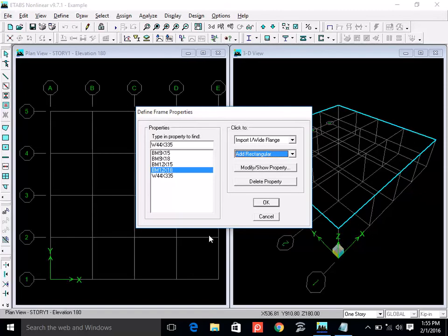So first thing you should do is ask for the drawings of previous projects. From the previous designs, you note down what sizes they are using, the format of the drafting, and how they write the general notes and other stuff. So you will learn the practice of this company, and then you can follow the same practice.